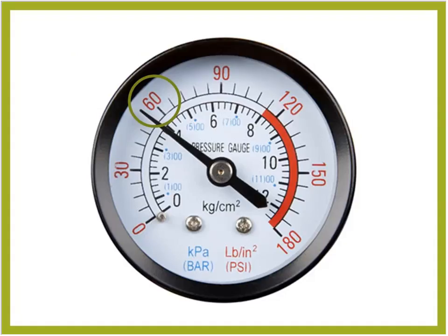You can work with a rater to do this, or you can purchase these water pressure testing kits. You want to make sure the water pressure is at least 60 psi. If it's higher, it's basically going to nullify those flow rates. All the flow rates, their ratings don't mean much because they'll all be higher if there's higher water pressure. Also, higher water pressure can lead to more leaks.